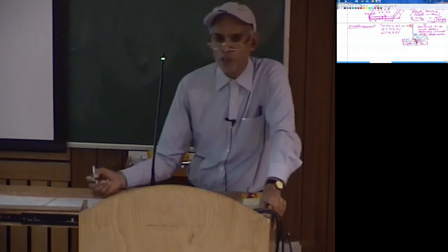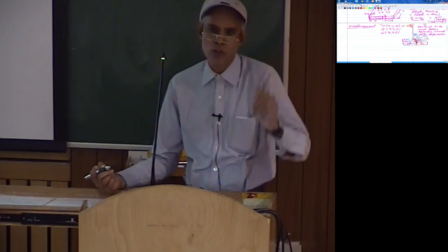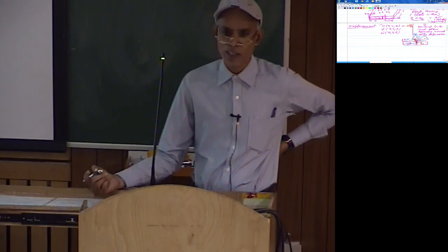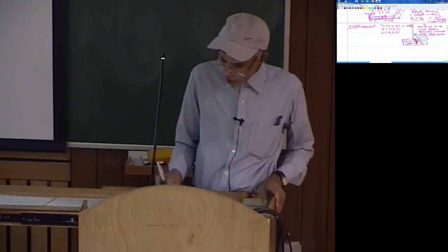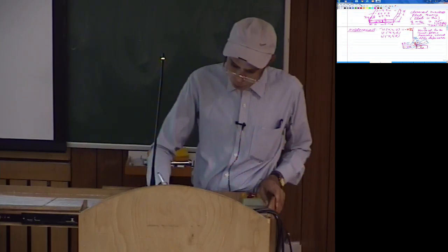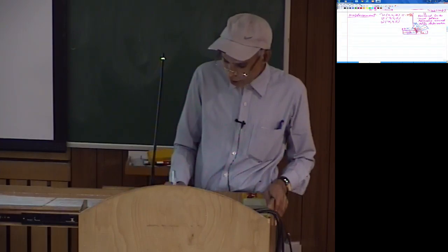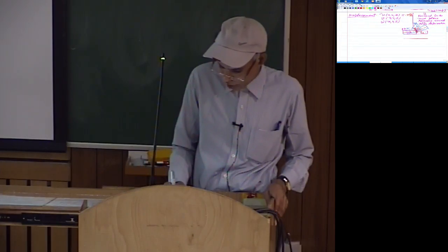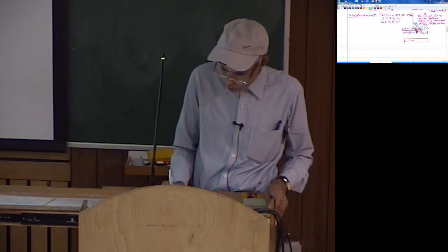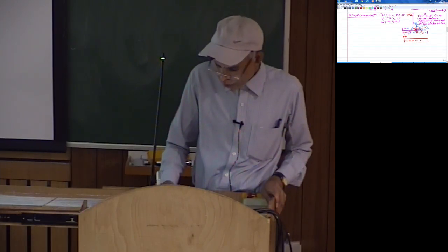This is similar to, if you recall, the Euler-Bernoulli beam where we had written u equal to, of course there I had taken the transverse direction as y, minus y into dv by dx. This is a similar concept. So this is in the xz plane. Now if I view from the positive x side, I can draw another view of this cross section from the other side. Say this is y and this is z. This is the undeformed configuration.